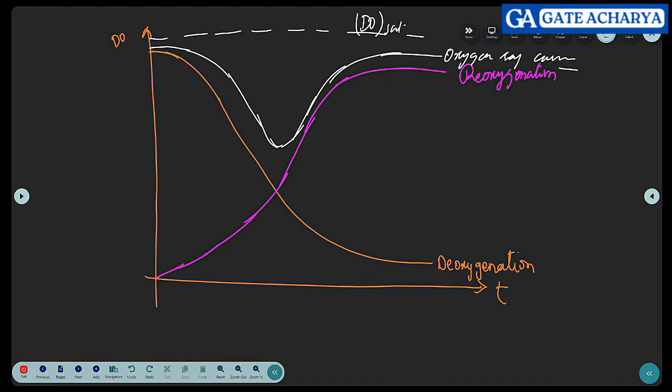Okay, listen. See, because of oxidation and reduction, the dissolved oxygen in the river water is getting reduced by means of deoxygenation. Initially the contaminant will be high, so a lot of dissolved oxygen gets consumed, and that consumption rate reduces logarithmically until it attains some constant value. This is called the deoxygenation curve. This is represented by the rate of deoxygenation, Kd.